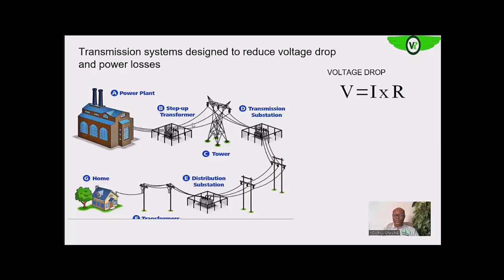So once the load starts coming into this particular system, you see that as the current is flowing back to the source of the power, there will be some level of drops along all of these copper conductors or copper wires that have some levels of resistance. It therefore means that if 11 kV is generated here, we will not have that exact amount of 11 kV here, because there are some drops along the line.